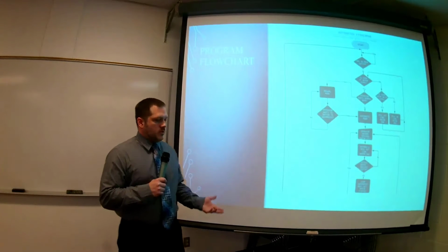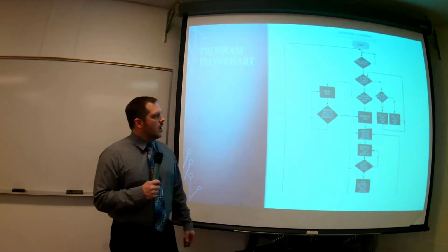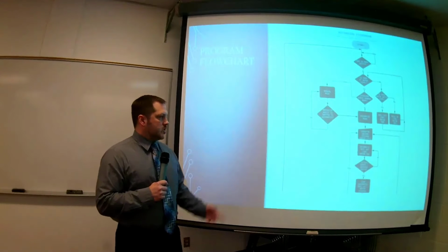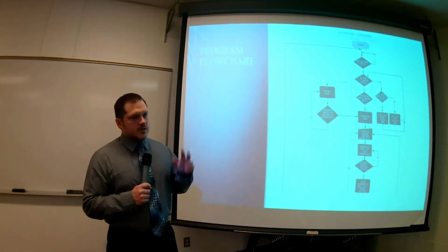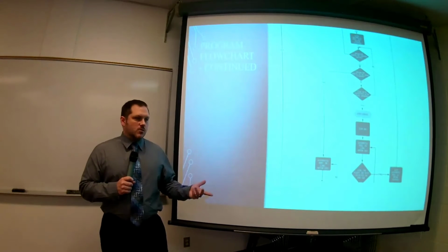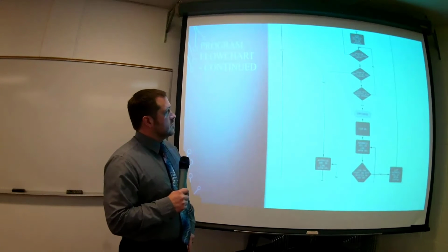Then we have the confirmation button, like when you're at your water level, you can go into manual mode, which is just going to let you reel in and reel out. That's all that's really going to do. And then you have your automatic mode. So you would set your depth, and then that's basically just doing a comparator. So you have your desired depth and your actual depth. When your desired depth and actual depth equal each other, it's going to shut the motor off.